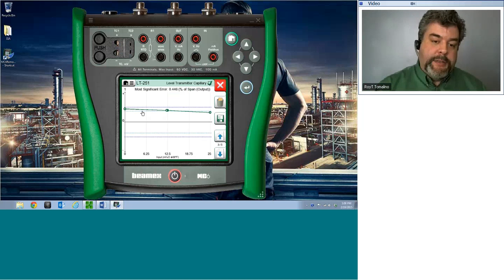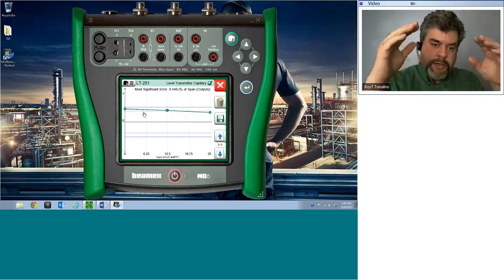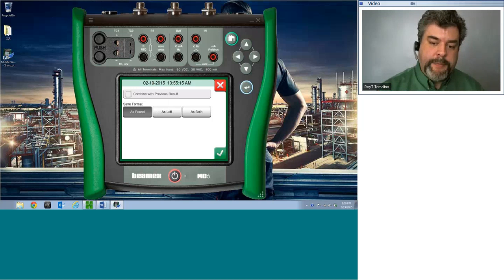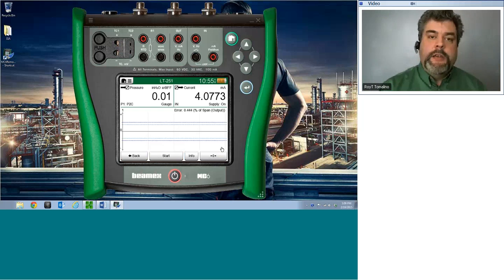So this inner band, what I'm saying here is that if it passes this threshold, then maybe it's a concern to our process itself. So it passed, but we need to pull it in underneath those guard bands. So let me save this. We'll save this as found. Next, we'll do an adjustment.